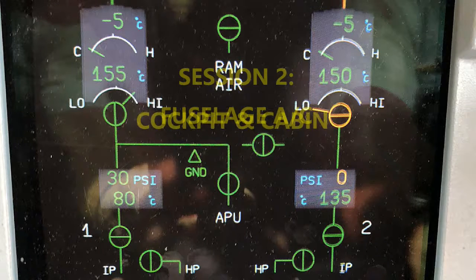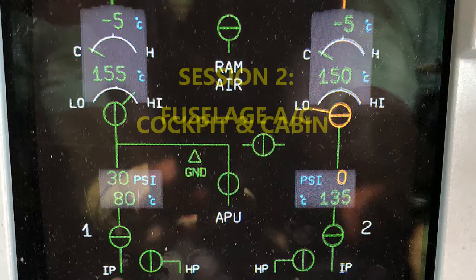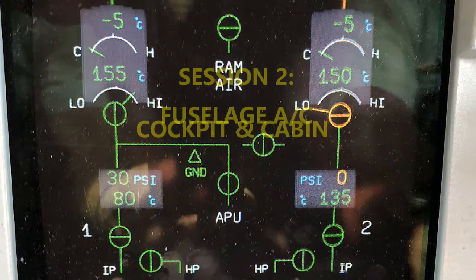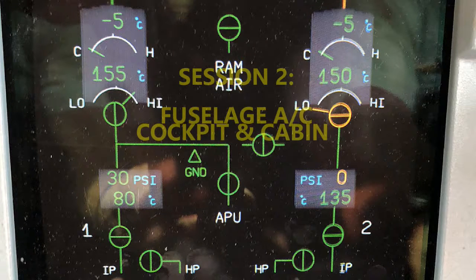Okay, and so remember I mentioned there's two computers with a zone controller. There's a primary and the secondary computer. If for some reason the primary goes down, the secondary is going to take over, but not at full capacity. It's going to be at a reduced level, but it will be able to at least meet the minimum requirements as far as the demands, until things can be fixed or replaced.